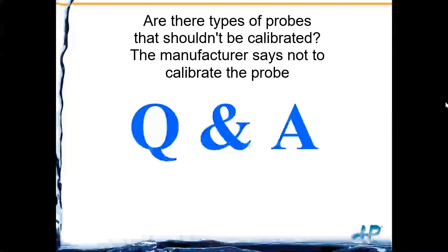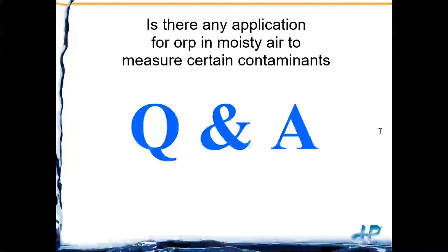If you have a manufacturer that's telling you that you don't need to calibrate your ORP probe, I think that's honestly a little crazy and ridiculous. If it's my company, please give me a call and let me know so that I can correct my support staff. But you have an ORP that is open to your process. If you don't correct for the plugging and coating that's happening, yes, you're going to be cleaning it, but if you're not also considering that, you're not going to get accurate readings. So it wouldn't be far off for you to be off, okay? So yes, calibrate.